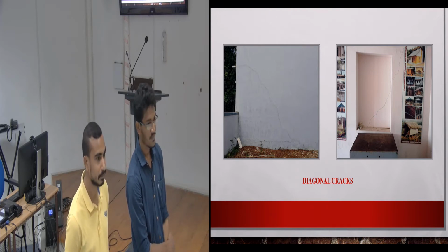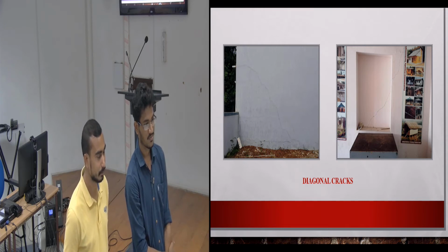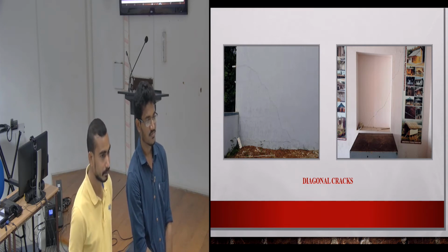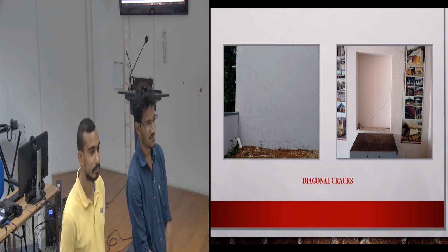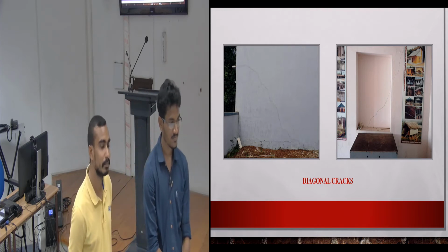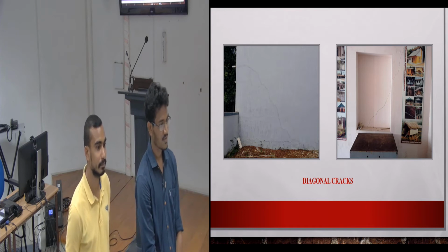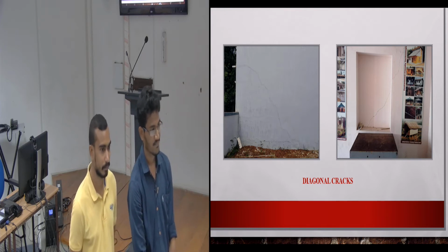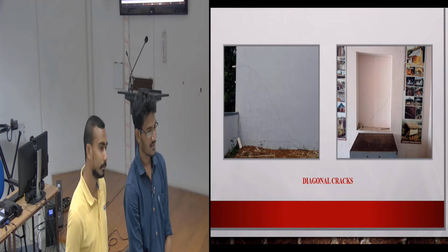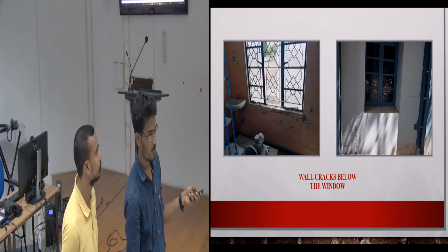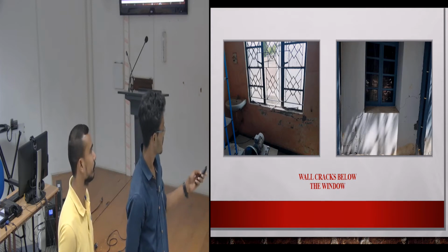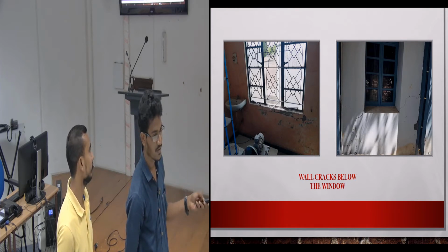Yeah, so those are very, very critical questions. Because if you were thorough, you would go to the other side and see. If you have the same crack on both sides, then you really have to worry about it. Okay, sir. Okay, go to the next one. Yeah, so that crack around the window frame is pretty big, in my opinion. How wide is it?